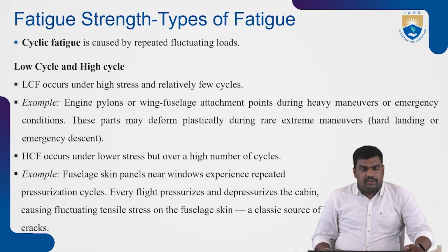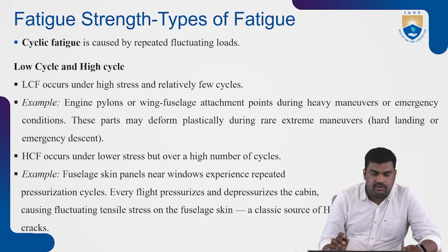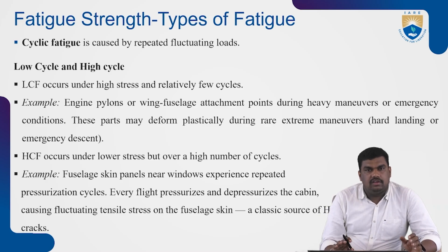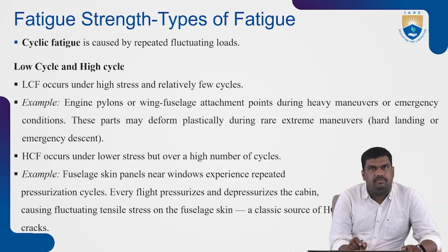So cyclic fatigue is caused by repeated fluctuating loads, as we know. There is low cycle fatigue and high cycle fatigue. So the types of fatigue we categorize into low cycle fatigue and high cycle fatigue. In low cycle fatigue, the name itself indicates that the cycles will be low. In that case, the stress will be high. So low cycle fatigue occurs under high stress and relatively few cycles.